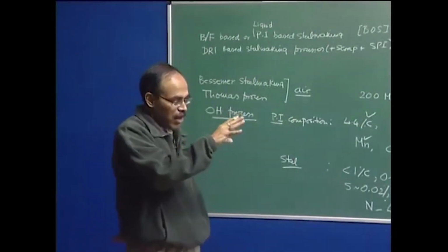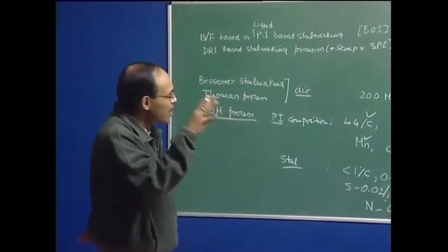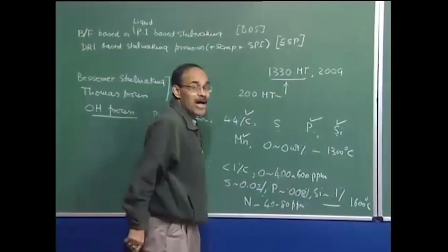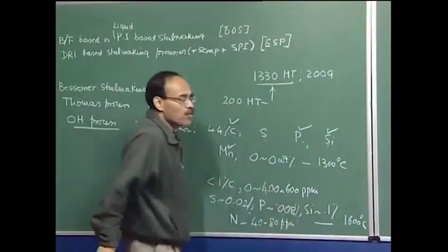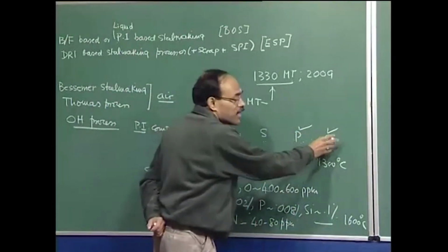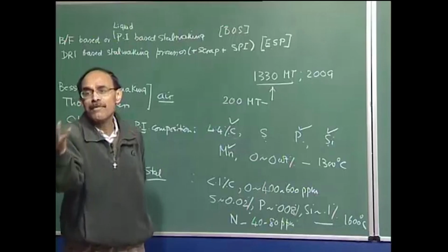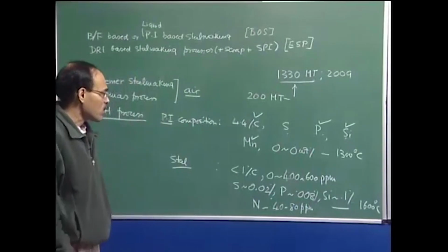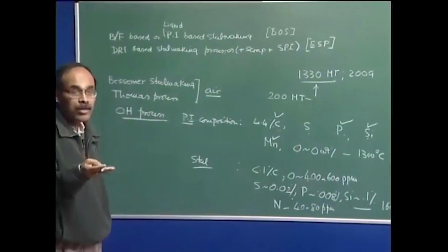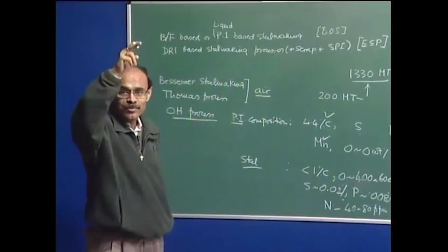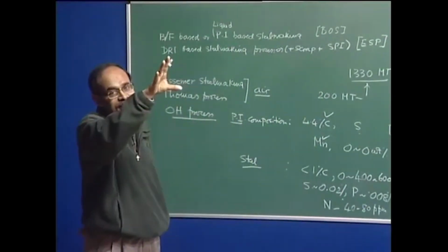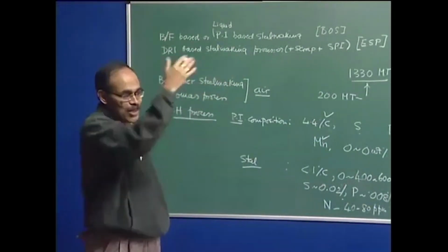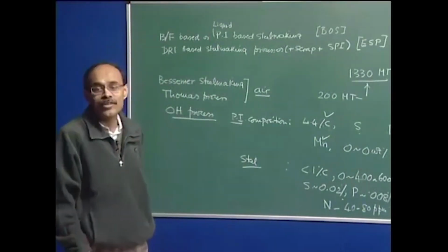So, the pig iron has more silicon and therefore less phosphorus, because removal of phosphorus, as we will see, requires highly basic slags. Removal of silicon may not require basic slag. If phosphorus is not there, you can oxidize silicon to silicon dioxide, fix it with iron oxide, and produce a ferrous silicate slag. We call that acid steel making process. In it, the converter lining is also going to be acidic, because if the slag is acidic and the lining is basic, the slag is going to eat up that lining, and the vessel will require frequent relining, which is not desirable.